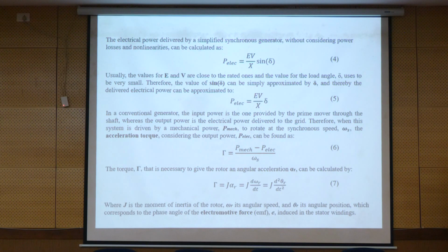Yeah, this is one thing, but it makes the system unstable, because if you change the value of V, it means that you are changing the value of the voltage over the load, and also E should be constant, otherwise your system generation is not constant. X is also the net, okay? But delta is not constant because the voltage is changing, because the currents are changing.